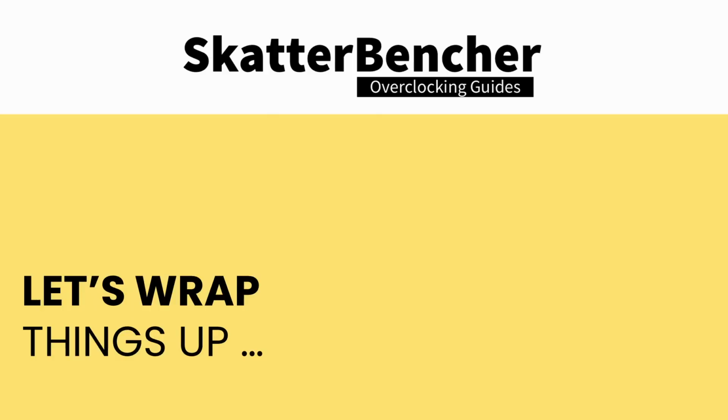In my SkatterBencher guide, I already highlighted that the standard voltage frequency curve of the Intel graphics for Arrow Lake CPUs is far from ideal. There's a lot of undervolting margin, and we can use that undervolt margin to improve power efficiency in a variety of workloads. For example, in this video, I illustrated that we can improve the generative AI performance in Llama 2 LLMs by about 40% by overclocking the graphics cores and the memory subsystem. Or we can undervolt at the standard frequency and improve power efficiency by about 4%.